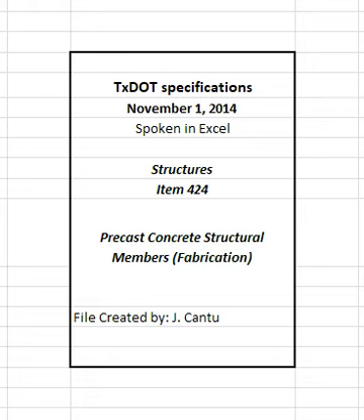Apply membrane curing compound with equipment and in a manner specified in Section 420.3.5, Spraying Equipment, and Section 420.4.10.3, Membrane Curing, respectively. Do not contaminate reinforcing steel, embedments, or concrete surfaces that will later be in direct contact with cast-in-place concrete unless the curing compound can be completely removed to the satisfaction of the engineer when applying membrane curing compound. Use membrane curing compounds that do not appreciably stain the concrete.